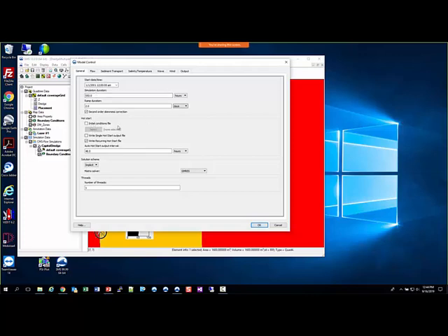We're not going to have an initial conditions file. We're going to have a recurring hot start file every 48 hours. It's already defined right there, so we would use that. Choose the solution scheme. We're going to go with implicit. And you can change the number of threads if you want. In my case, I have some extras, so we go up to the maximum of 4.